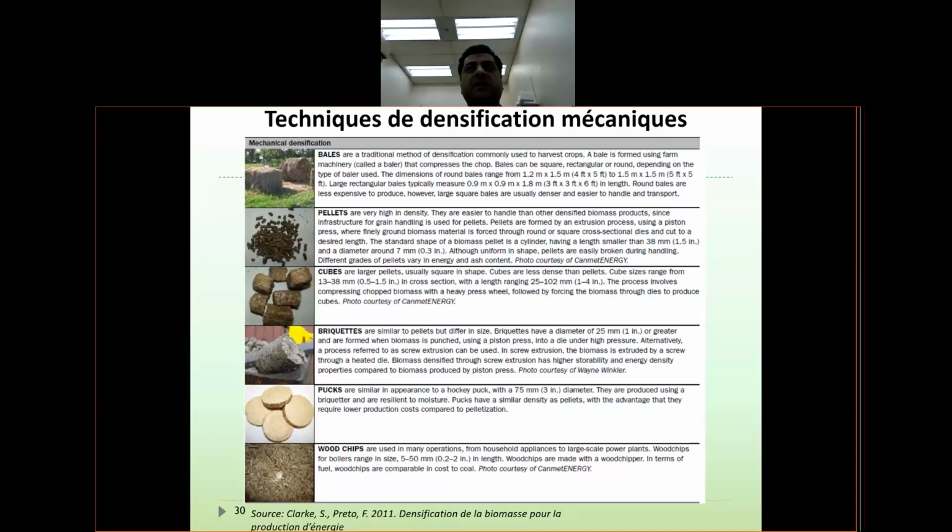specific publication, they used only a hammer mill, a hammer grinder. If they change the type of the hammer, or even the type of the mill itself, the results will be different. For example, in their own example here, they just changed the opening of the screens below the hammer, and by changing the openings, the values of energy consumption differ. So I want you to read the article and get familiar yourself with more insights into grinding and the associated parameters.